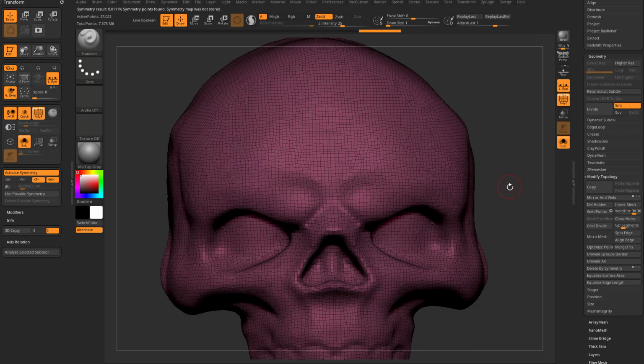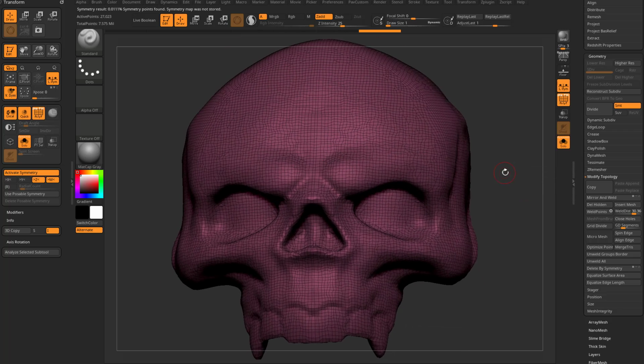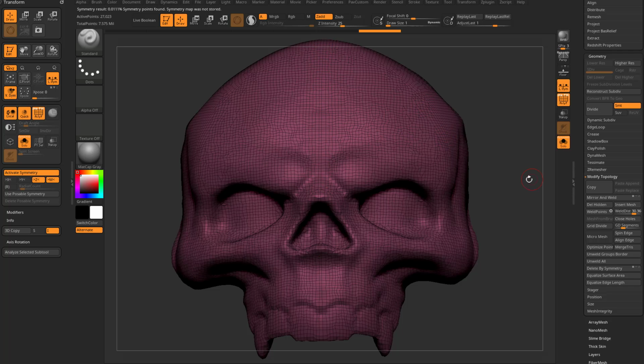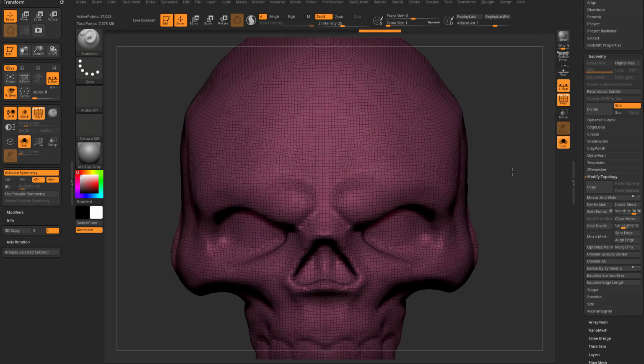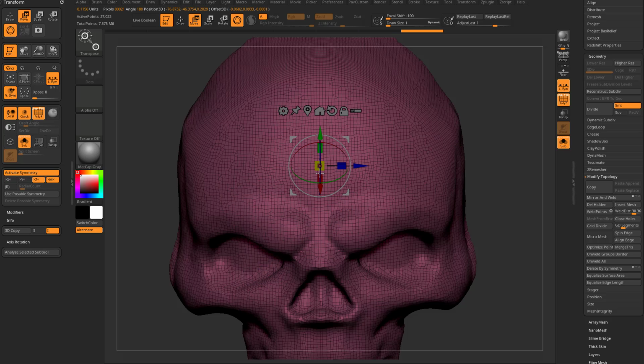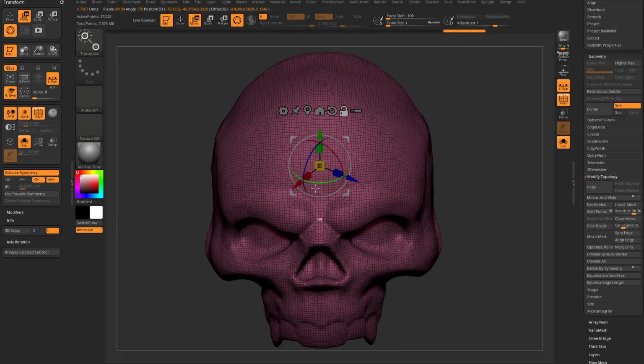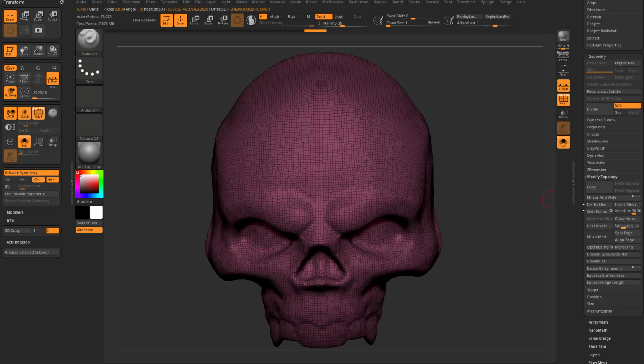Because if we look in here, it's an old Dynamesh, and I probably scooted it around a bunch, and you're going to see there is no actual midline for this object, which is kind of a bummer because if I go in here and hit W, and then want to do the old trick where I hold down Alt and drag to another point, there is no midline point to drag on. So again, if I hold down Alt and Shift and make this 90 degrees, I can say mirror and weld, and it's pretty close, but not quite.